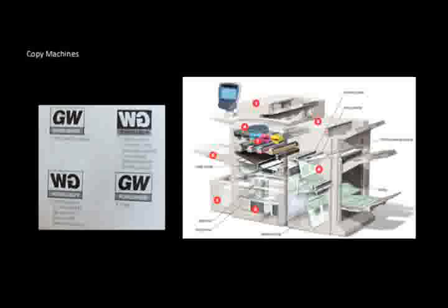The negatively charged paper passes under the drum, transferring the toner to the paper. The toner is fused to the paper as it passes by a heater. The paper is ejected to the outside collection tray.